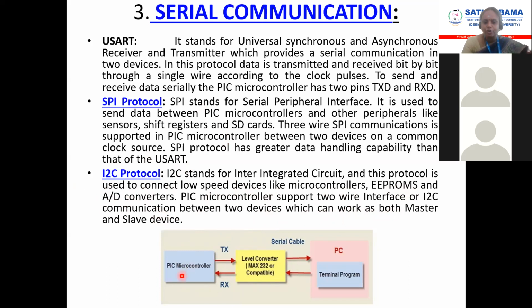My PIC microcontroller has a TX and RX. You have seen that MAX232 cable. You will study in detail how it transmits in your 4th unit. All the serial communication protocols you will study in detail, that's why I'm not touching the protocols here. You have to know what serial communications are adopted in PIC: USART, universal synchronous asynchronous receiver and transmitter; SPI, serial peripheral interface; and I2C, inter-integrated circuits.